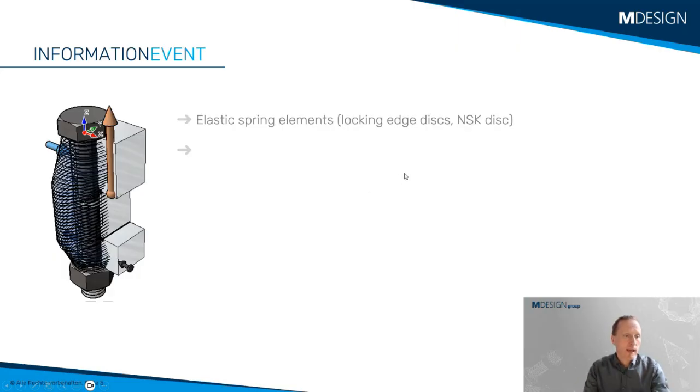It's really complicated in the calculation because it must be iterative, using the VDI steps, because the elasticity of the elements depends on the preload, and the preload, of course, depends on the loss of preload by embedding, and this, of course, depends on the elasticity of the elements. So, of course, only an iterative approach is possible to get the real situation. So you can use it. In 2024 you could also use spring washers, but only under the head. Now you can use spring washers and all these other elements under the head and under the nut.